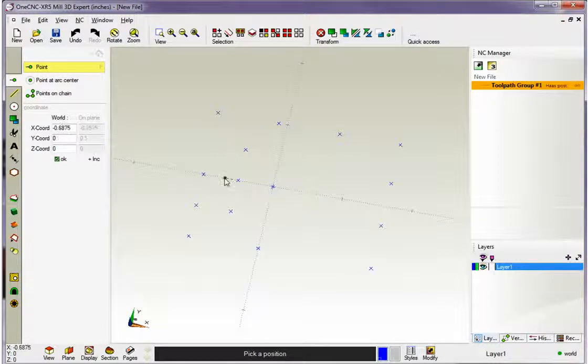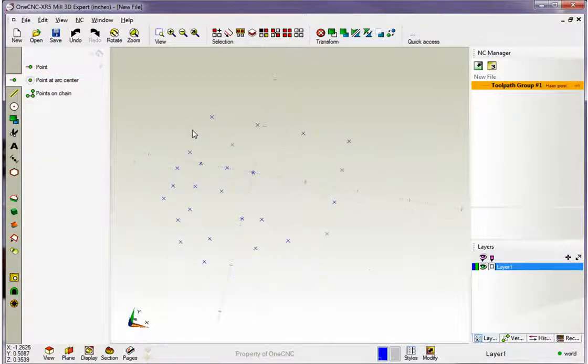Now what if you don't want a grid snap? Well, if you don't want a grid snap, just hold the tab key down on the keyboard. As you hold the tab key down, that disables the grid snapping, and it also disables the referencing off of existing geometry. You can see there's no more dashed lines here, so I can left click anywhere that I like. As soon as I let go of the tab key, we're back into grid snapping and referencing off of existing geometry. Very easy. Alright, let's take a look now at creating arcs.